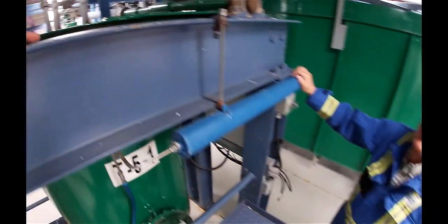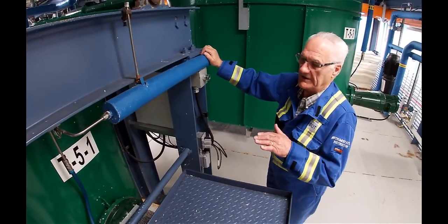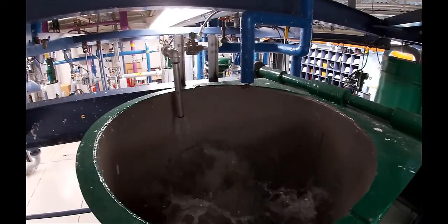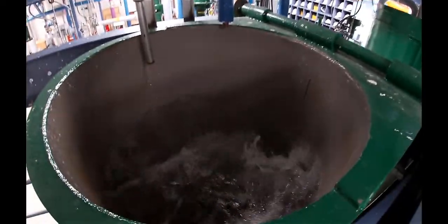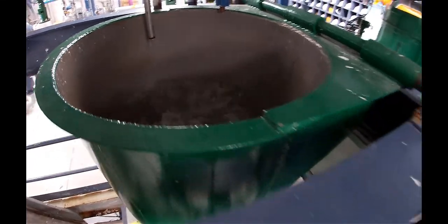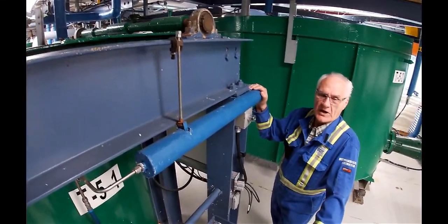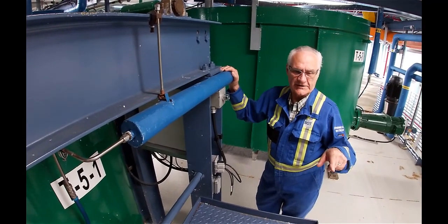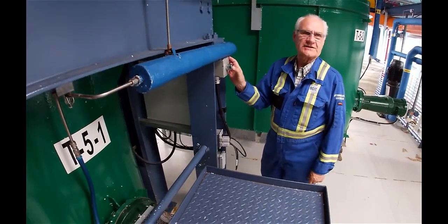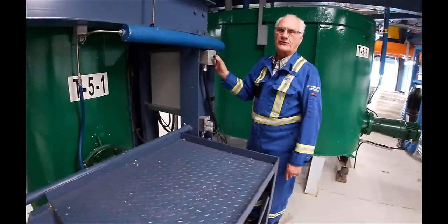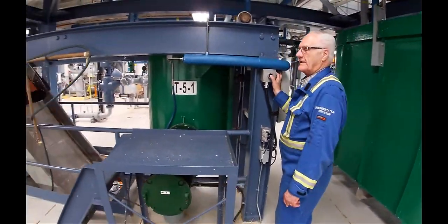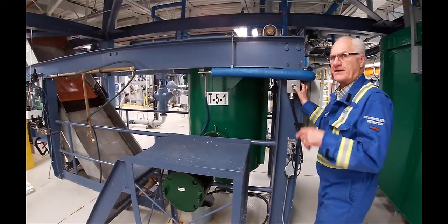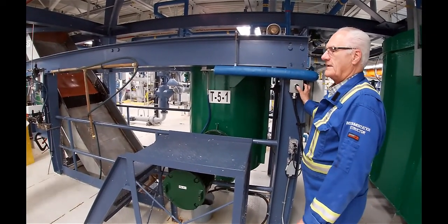Get to 170 gallons in there. Once we get to 170 gallons, it will start the agitator. So the next step in this process is to now add 80 sheets. For each sheet that Mari puts in there, I'm going to push this little button, and it's got to turn green in color when I push it, so that the DCS downstairs can count the number of sheets that are going in.